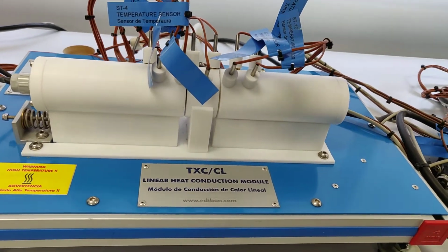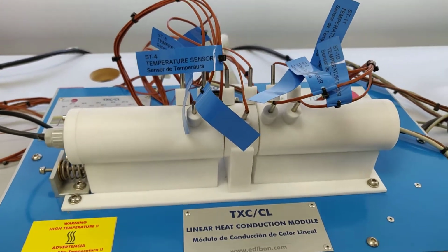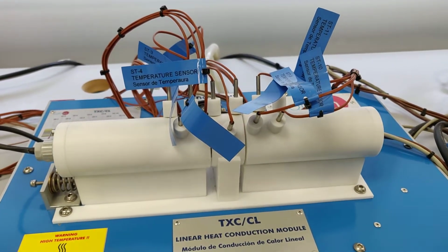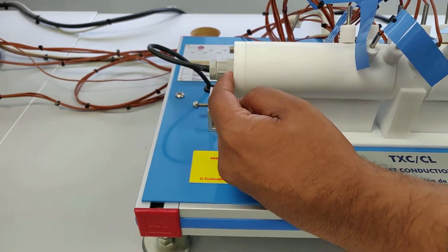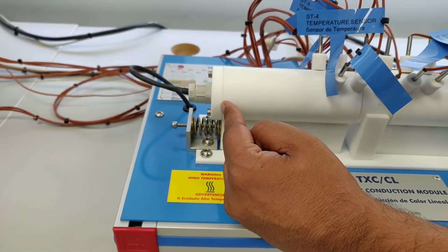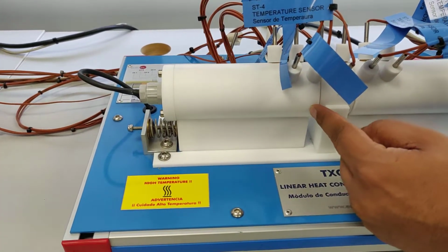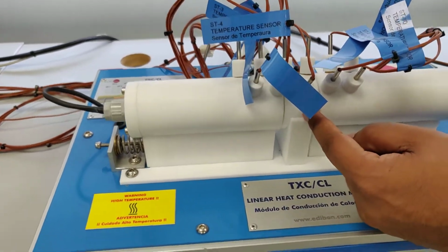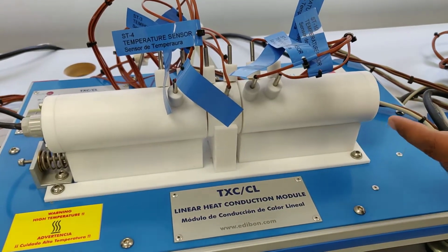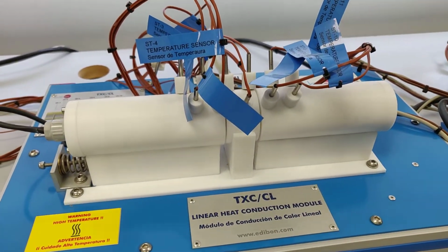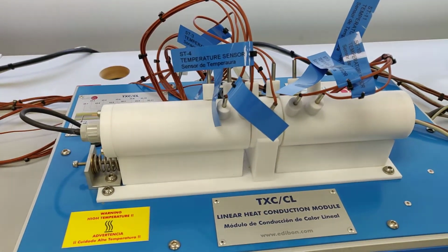And in the middle section we are going to place the test specimen for which we want to check the conductivity. So what actually happens is the heat that is given on this end will travel all through this metal inside, and then it goes into the test specimen. Through the test specimen it goes to the other side, which is the cooling section. So the movement of heat is from left side to the right side. You have the source of heat here. Electrically you are heating that side.